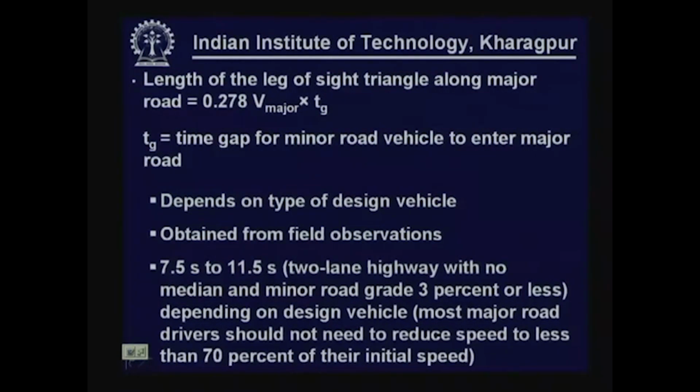But if we use this time gap of 7.5 to 11.5 seconds depending on the vehicle type, then vehicles on the major road will normally not be required to reduce speed to less than 70% of their initial speed.